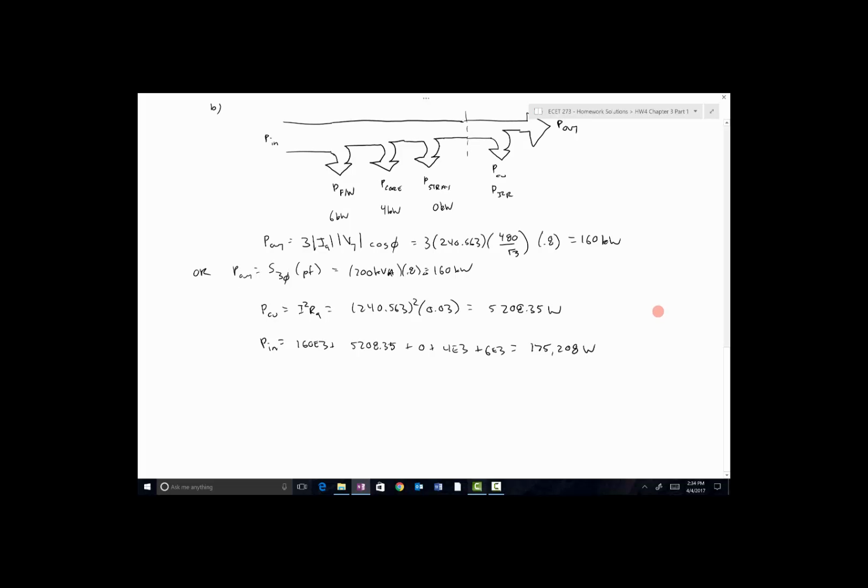And then it asked me to determine how much torque needs to be applied by the prime mover to deliver this much input mechanical power. And we know that the relationship between torque and power is just we take the torque and multiply it by the mechanical rate of rotation of the prime mover. So that's at the input, P in, power from the prime mover has got to be the torque applied by the prime mover times whatever speed the prime mover is rotating at in radians per second.